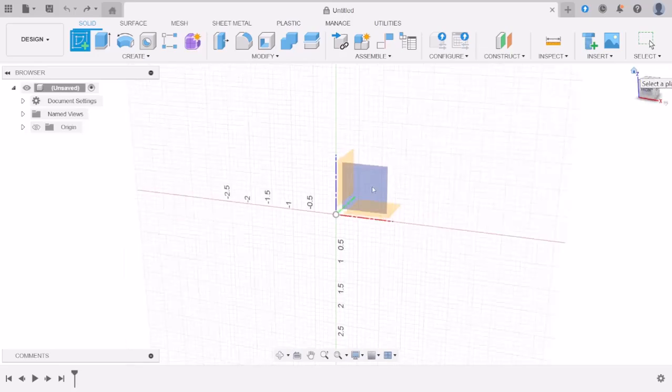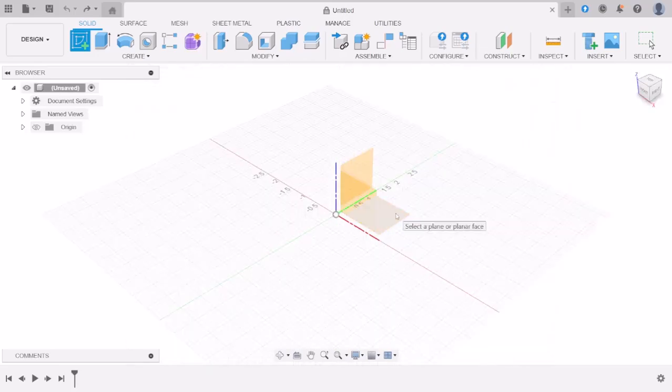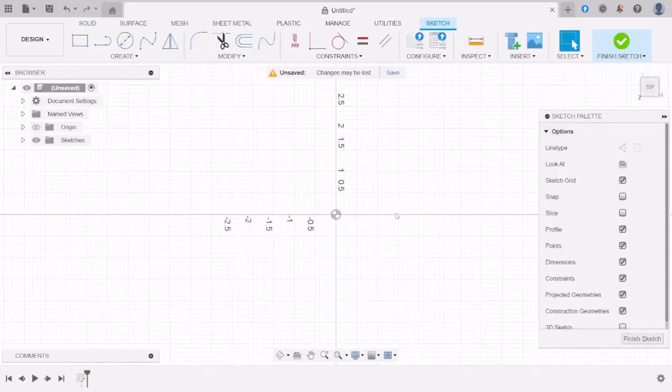Either way, let's assume I want to create my sketch here from the bottom and build up. Just to point out, this place I said is the bottom is just a reference point created by Fusion so you can stand off something. It doesn't restrict me from creating anything below this point.